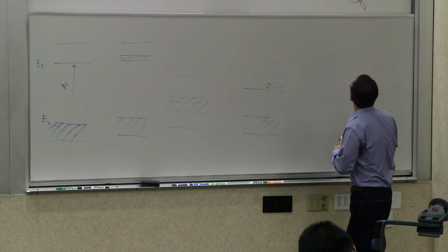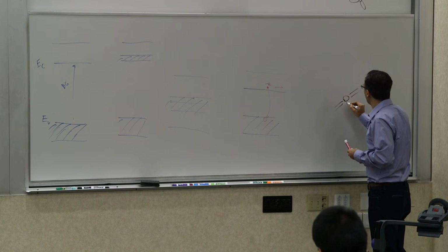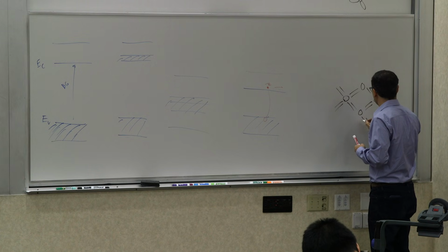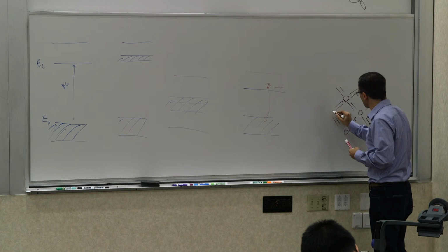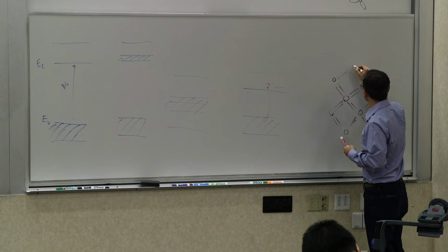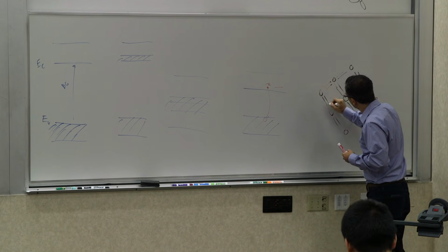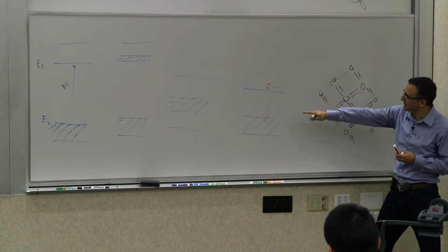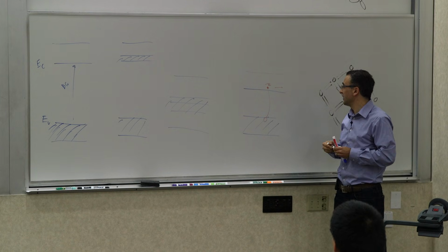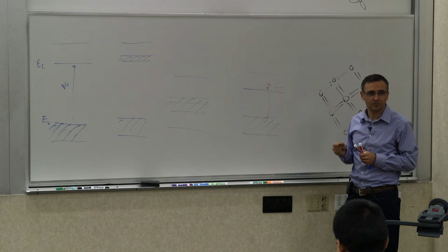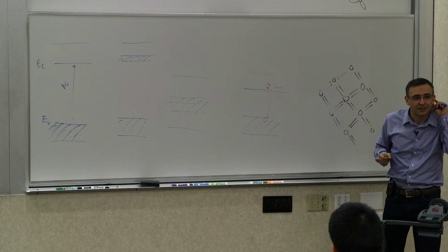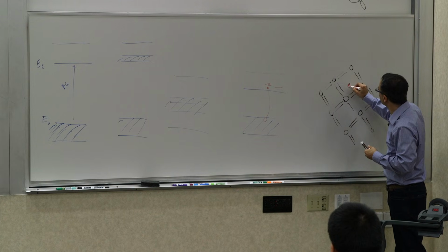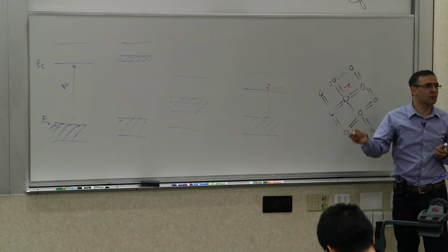In this picture that we had up there, that corresponds to a simplified view. Let's redo this quickly. You may have already seen this picture, but it's okay. What does it correspond to in this picture? This process is called, by the way, thermal generation. Yes, a bond breaks, right? So this one breaks, and an electron is freed. Now this electron can move around.